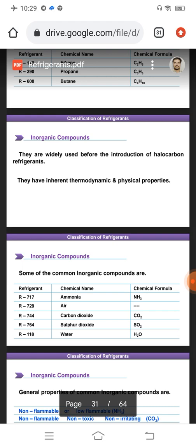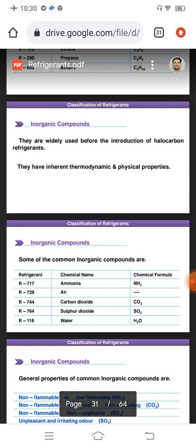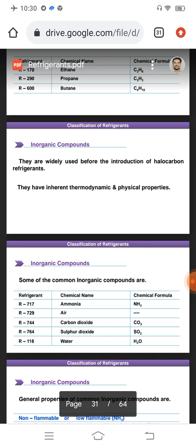Cryogenic fluids are those applied for achieving temperatures from minus 160 degrees Celsius to minus 273 degrees Celsius. Above this range we can use a multi-stage refrigeration system to reach the desired temperature. But below minus 160 degrees Celsius this is not possible, since the COP of the cycle becomes too low.